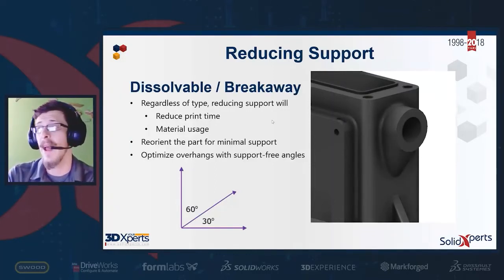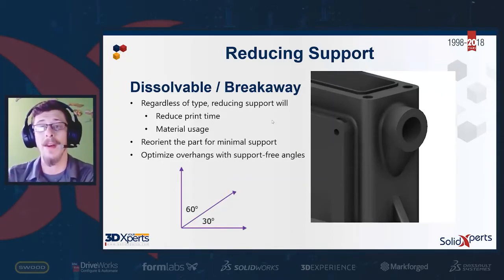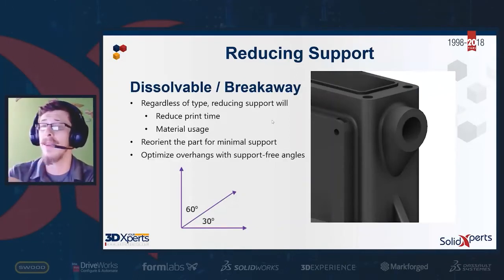can be virtually eliminated by just adding a loft. Now, this does add a little bit of extra material, and then you do have to identify if it's going to outweigh the amount of support and the print time. But by having a feature just like this can then eliminate the need for supports.